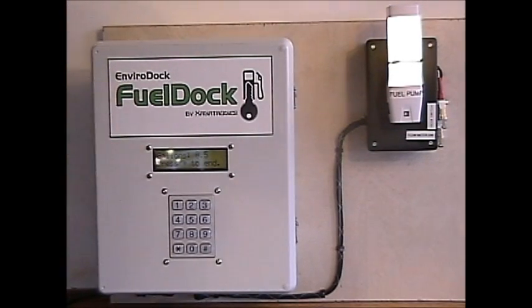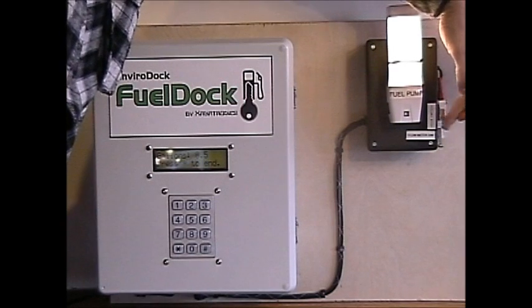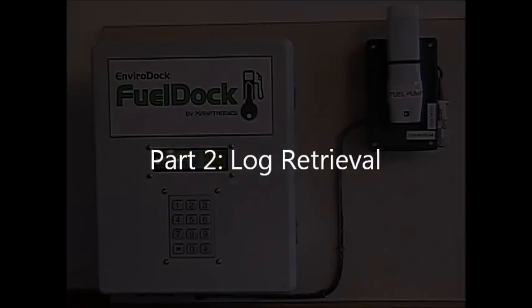Once a reasonable count has been reached, we simulate the operator putting the fuel delivery nozzle back on the hook by pressing this button, which is the hook switch. That de-energizes the pump. It displays how many gallons total were pumped, and then it returns to the original screen. We're ready for another operation, just like before.